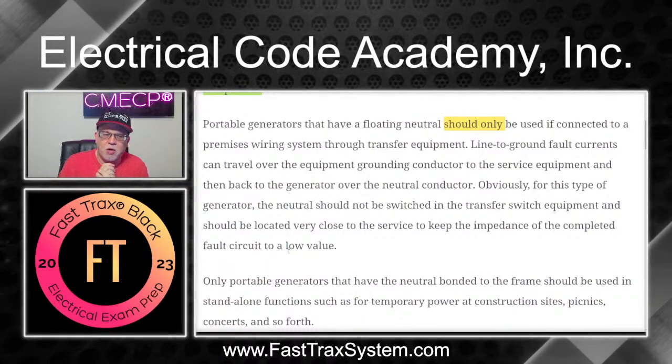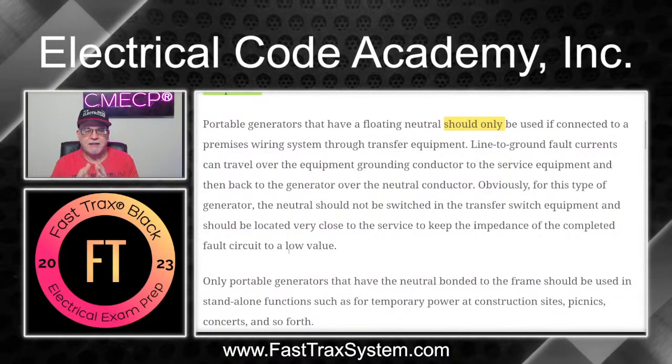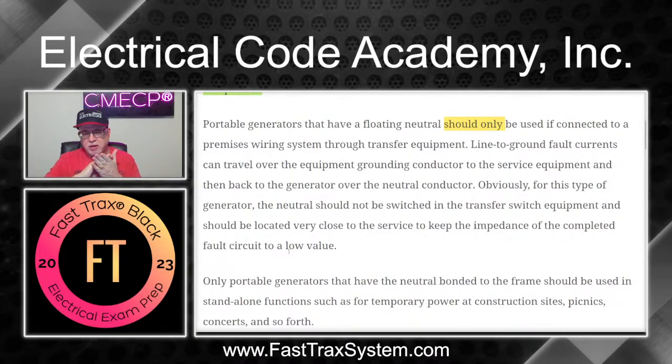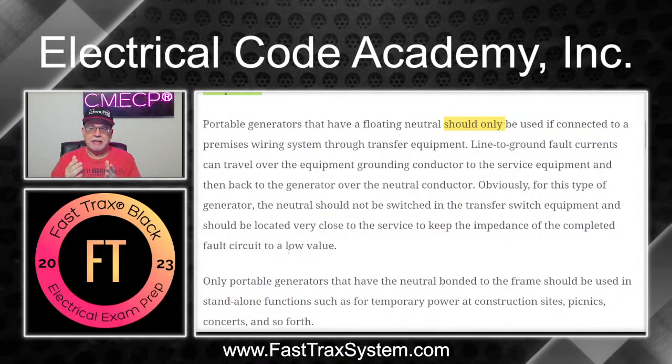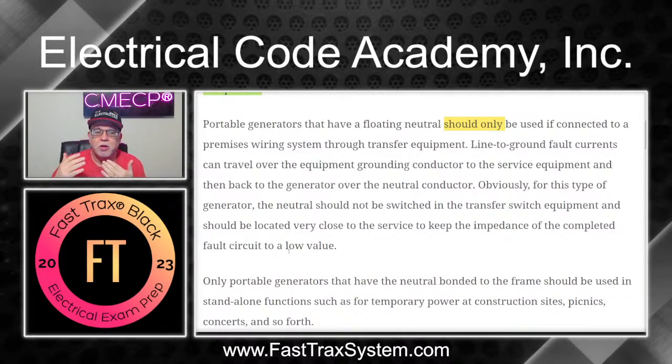One of the biggest things that I always run into with people is when they do a generator for their house and they determine whether or not, depending on what happens in the transfer equipment, right? If the transfer equipment switches the neutral, okay, just breaks the neutral, then what you have is a separately derived system. Now, if it doesn't switch the neutral, then it's not a separately derived system. So it's important when you're selecting the equipment to know what you're doing. But don't worry, we're going to dig even deeper. We're going to look at this.